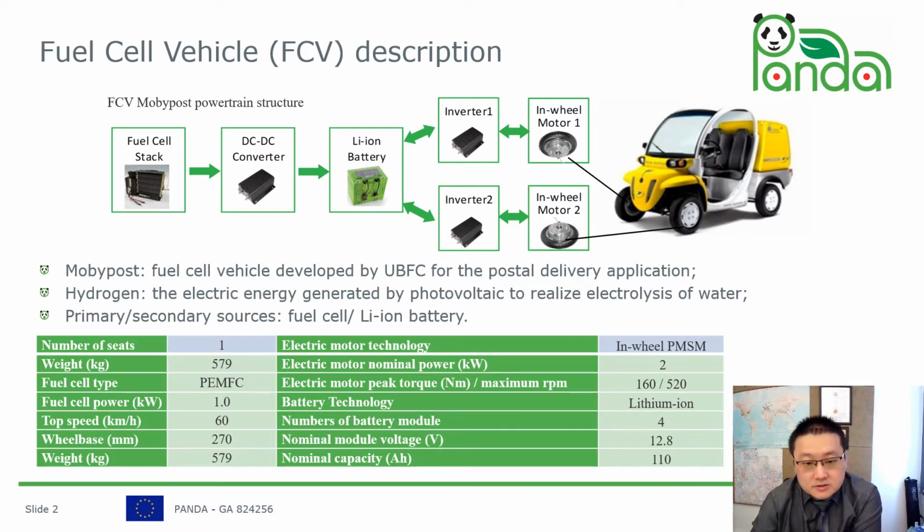The entire powertrain is a hybrid one. We don't have an electrical charger in this vehicle. We only have the hydrogen supply part, so the fuel cell, in addition to doing the propulsion of the vehicle, should also be used to charge the batteries.